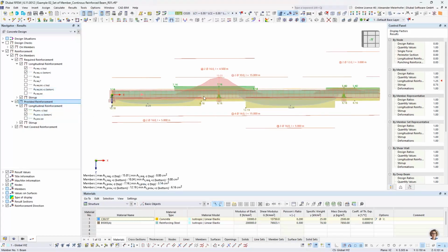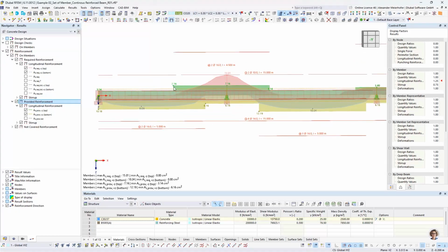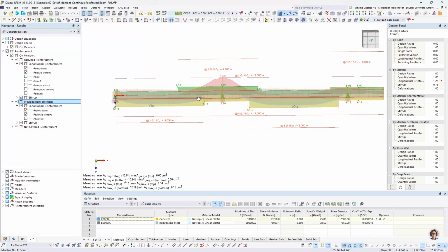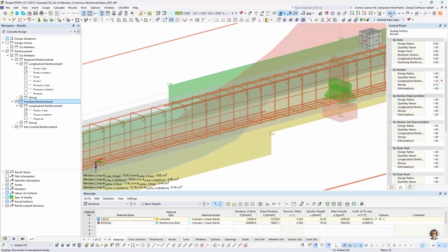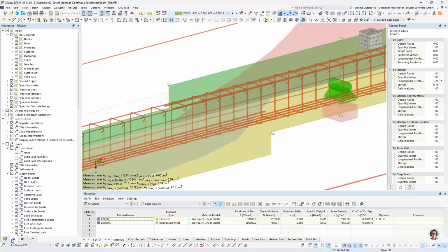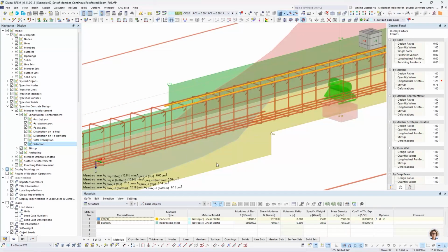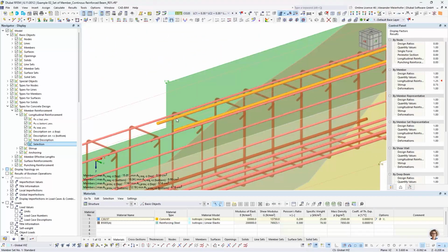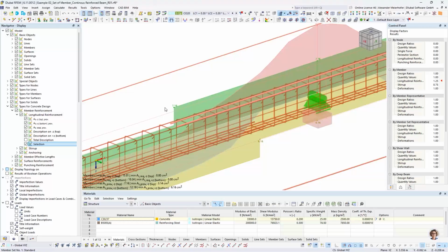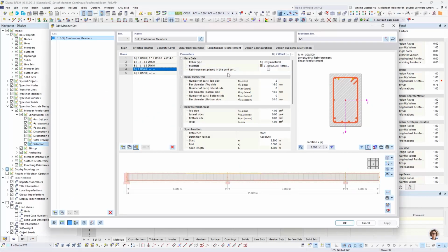But if we design with realistic reinforcement, we can compare it. We have all the tools in RFEM 6 which we need. So we see here over this support, my provided reinforcement is too little, I need more. To define more values, I will go inside. I can also select the rebar normally, types for reinforcement. I have to make sure I deactivate the reinforcement, but I want to select the rebars now. You see, with the selection activated, I can select these rebars. This was my additional reinforcement. With a double click, I come directly to my rebars, and I know these are too little.